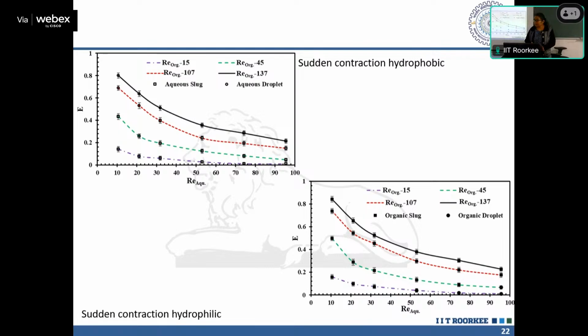So it is not only one factor that is giving you the idea. Any transfer rate, whether it is reaction or mass transfer, is governed by two things. One is the specific area of contact. Second is the residence time. If you recall, in such cases the transport process is governed by molecular diffusion, which is a slow process.